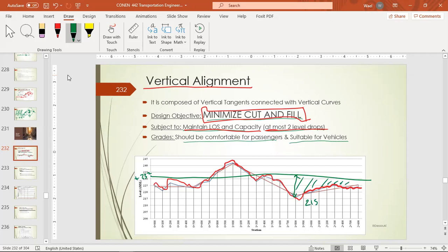We have almost 17 meters depth. Filling a 17 meters depth is not an easy job, because we have to do it in layers and make a quality control check to make sure that it's compacted before we pave the road.